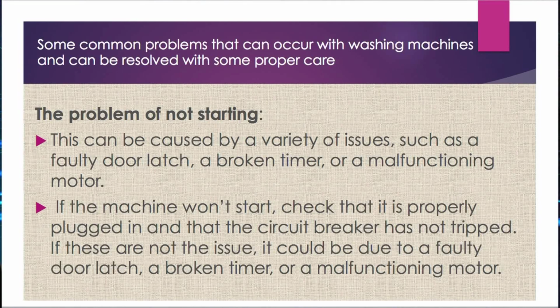This can be caused by a variety of issues such as a faulty door latch, a broken timer, or a malfunctioning motor. If the machine won't start, check that it is properly plugged in and that the circuit breaker has not tripped. If these are not the issue, it could be due to a faulty door latch, a broken timer, or a malfunctioning motor. In this case, it is best to contact an authorized service center for repair.